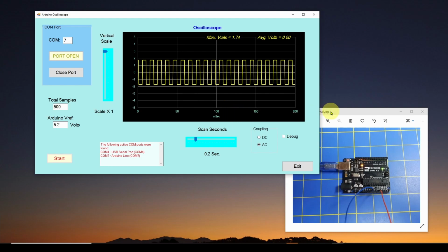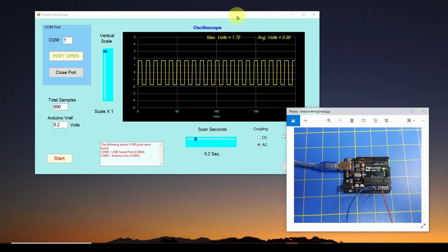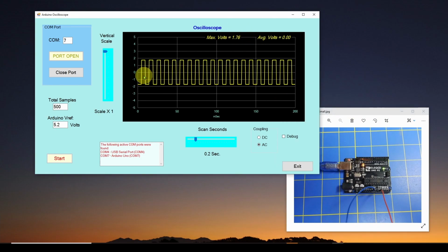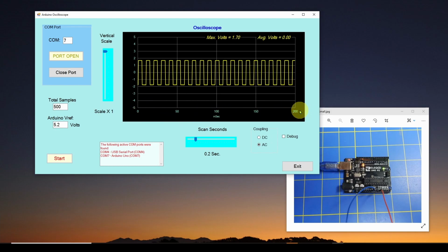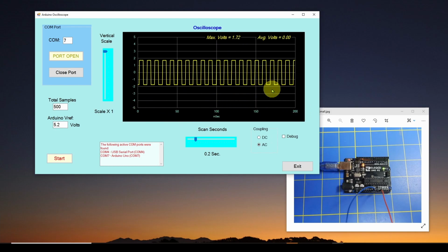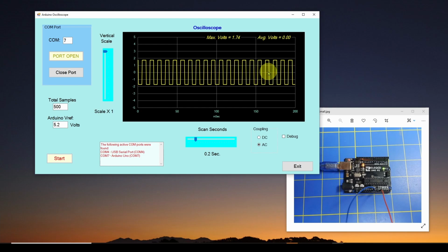One of them was the limitations of the Arduino. And one of the big things we talked about was the memory limitations, the onboard memory. So for example, we're going to be grabbing, you can see here, 200 milliseconds worth of data that's being continually updated. So that data has to be stored on the Arduino somehow before it's sent to the computer.